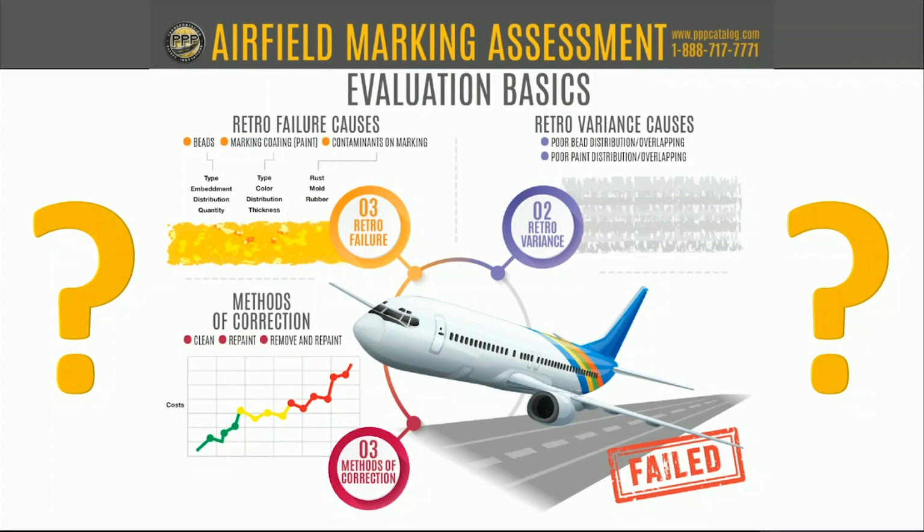I like that. I like that description. I'm the same. I like to see that. The next question is, by the way, one of the best things to have out there in the field is a little wet mil gauge. You're going to want your type 1, type 2 paint to be around 13 to 15 mils thickness, and then type 3 you can go up to 20, 25 mils.